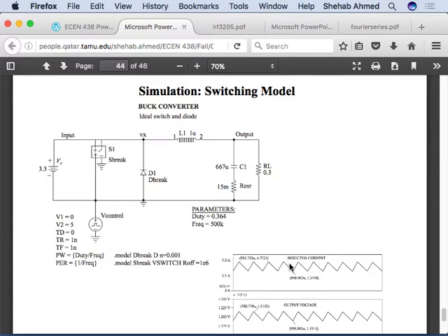The ripple will be purely controlled by the switching frequency and the value of the inductance that you've chosen. Purely, L is equal to delta lambda over delta I. You've chosen a certain L based on a certain value of input voltage, output voltage and switching frequency. That's it. The ripple will not change. So why bother with a very detailed switched model in your simulation process when you can go to an easier model? That's one reason we try to come up with a model for the circuit.